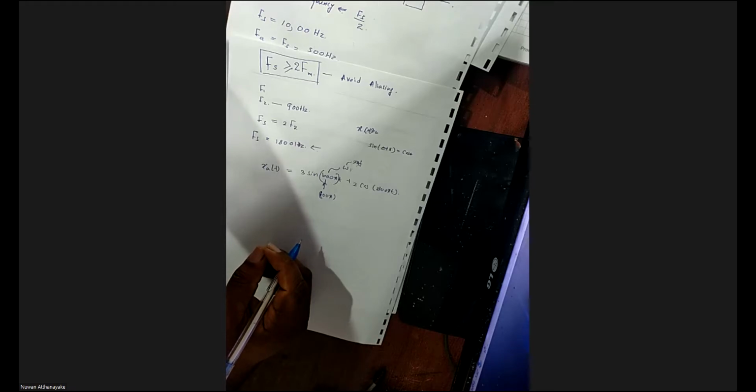But to evaluate the Nyquist rate and related stuff, we want to extract the frequency only, so for that component it won't matter whether it's a sine or cosine. But once you do the discretizing, if you have a kind of phase shift, it really affects the discrete version. Yes, so that's the one I want to highlight.